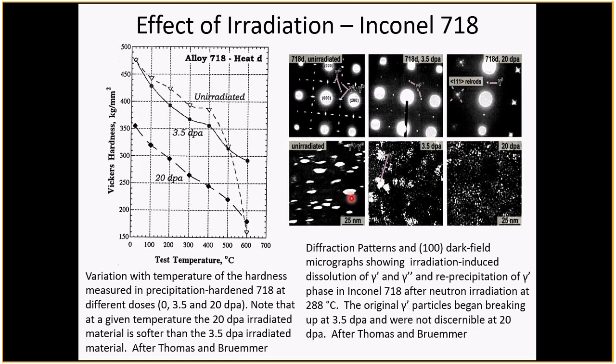And this is simply because you've concentrated elements, 25% in this case, of the material is aluminum in this zone. And that 25% changes the lattice, and that also makes it harder for a dislocation to pass through, in addition to the ordering. So you have two things imparting strength.